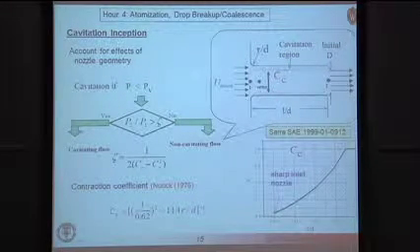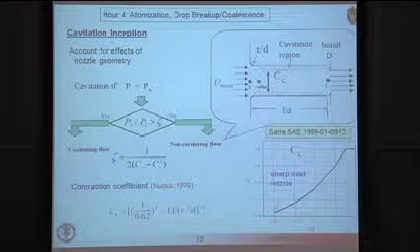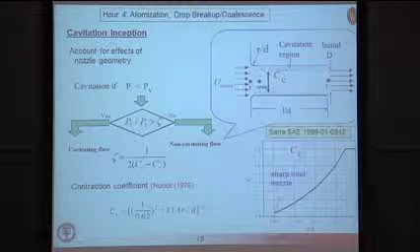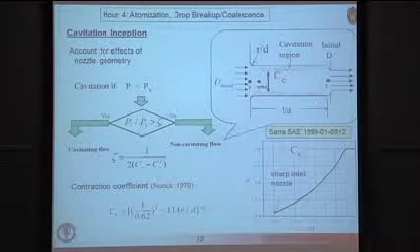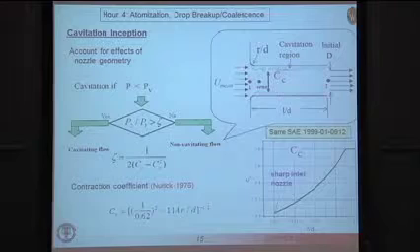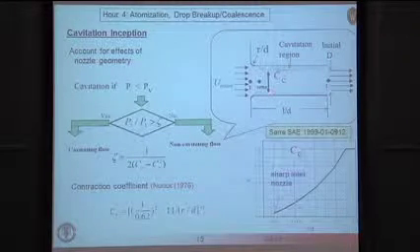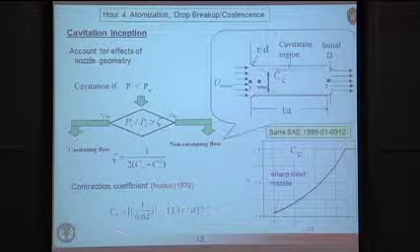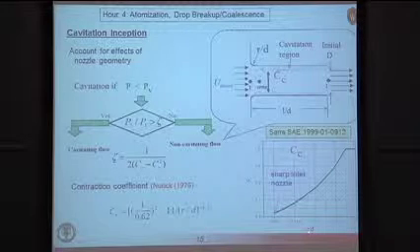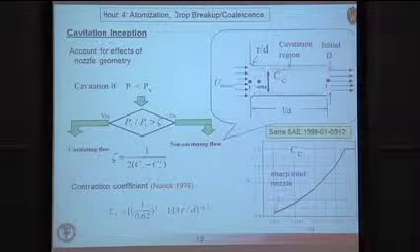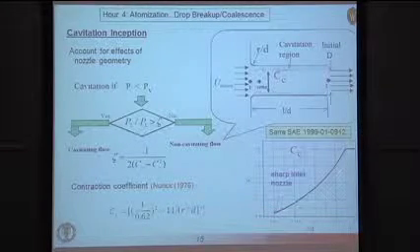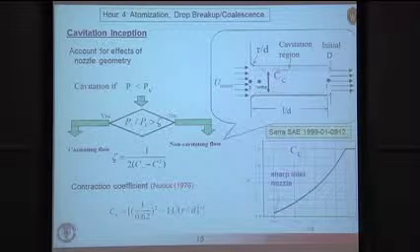So here's an example of a simpler model that is used in many of the CFD codes that we run. Basically, here you have your reservoir supplying flow. It enters, in this case, a straight hole nozzle, but with an entrance radius of curvature. There is a separation that takes place at the so-called vena contracta here. That's determined by this contraction coefficient, and there's experimental data available to tell you how that contraction coefficient varies with the radius of this entrance to the passage relative to the diameter of the hole, ranging from a sharp edge hole up to a fully detached flow.